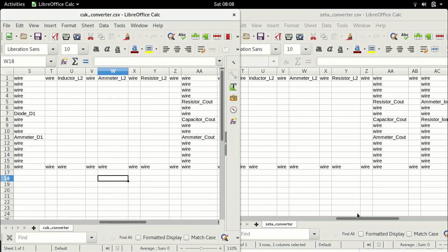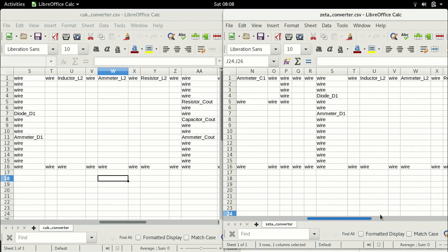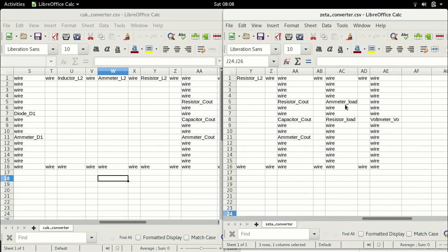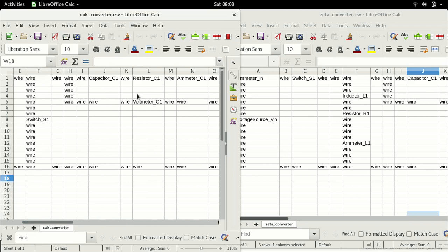Right? Here in the case of a ZETA, the capacitor is not connecting two parts of the circuit. Both parts of the circuit are being connected. When the switch is turned on, the output is connected to the input. Right? So the capacitor doesn't play a connective role. The capacitor is merely an energy buffer. In this case, the capacitor needs to be much larger and the current is going to be much different as compared to the current here. And that is what we are going to examine.